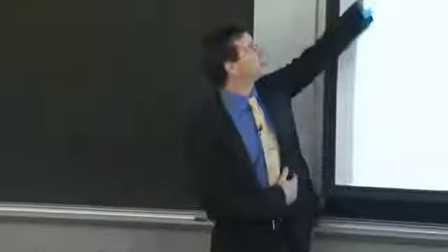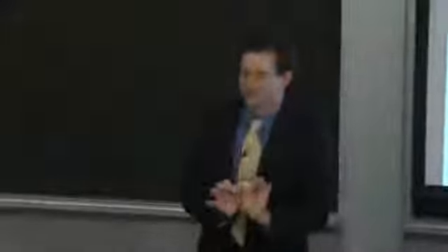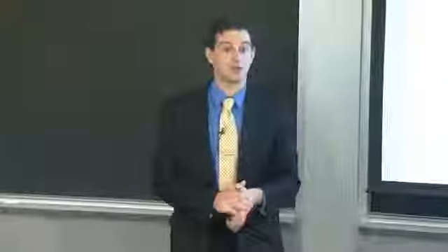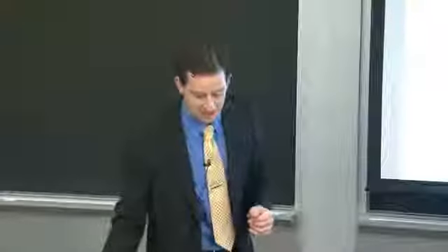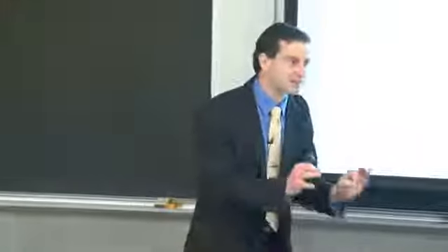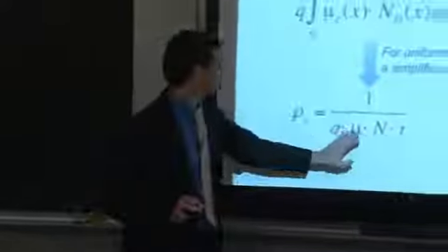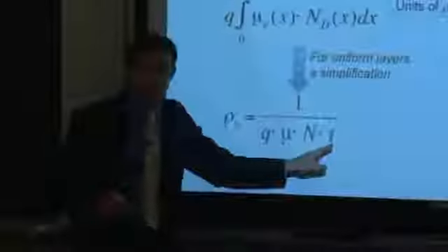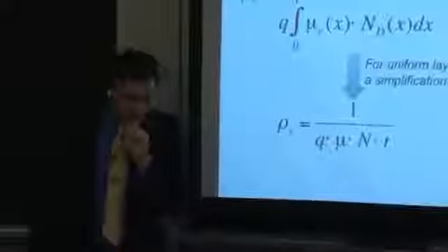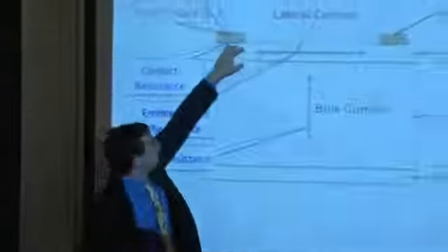And oftentimes, the resistivity of a material, you might spend months trying to optimize the resistivity of your emitter region. For those doing thin film materials, you might be working on zinc oxide, aluminum doped or fluorine doped zinc oxide, for instance. And after months of tuning the temperature and the oxygen partial pressure during the deposition process, you're there and you have what you have. You have a certain carrier density and a certain mobility, and you can't do much more than vary the geometric parameter, varying the thickness. So what next? If my thickness is too big on my emitter, I'm going to be absorbing all of my short wavelength photons in the front surface of my device.